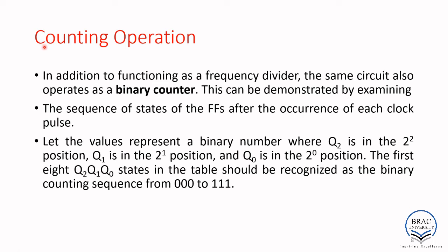There is one more application of the flip-flop, which is the counter, which we already discussed in the last lecture, right? The sequence of states of the flip-flops changes after the occurrence of each clock pulse. So let the value represent a binary number where Q2 is the 2 to the power 2 position, Q1 is 2 to the power 1, and Q0 is 2 to the power 0.